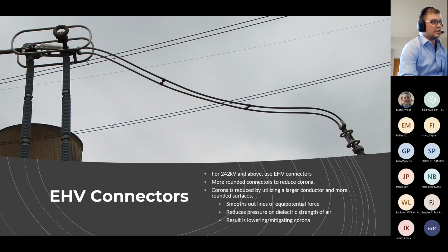You can notice even the barrels have been shortened a little bit, and even in a regular style situation of a compression terminal connector, you can order a short barrel if it's a situation where you don't want the barrel to be too long because you're worried about electrical clearances or any issues like that. But you'll also see here that they still used a compression for this specific connector.